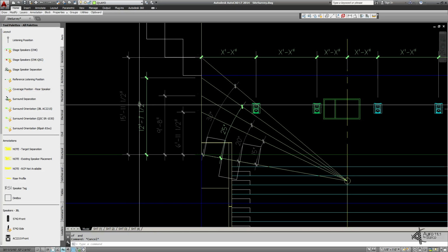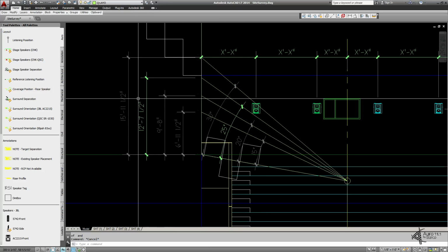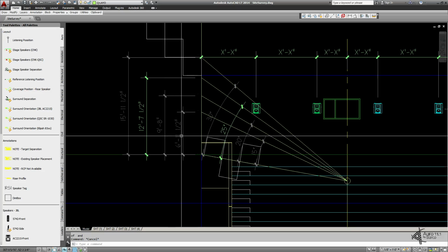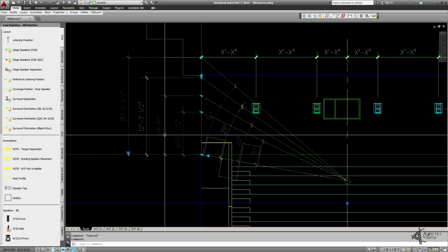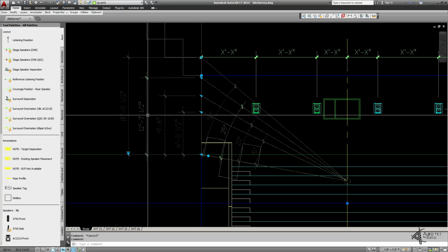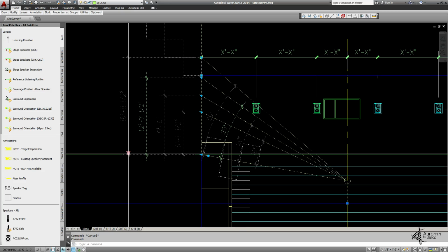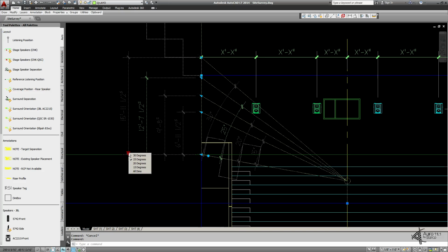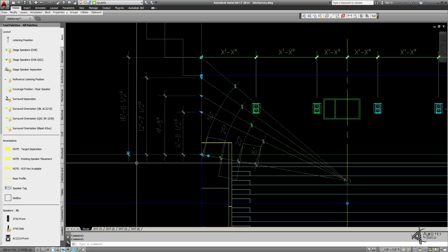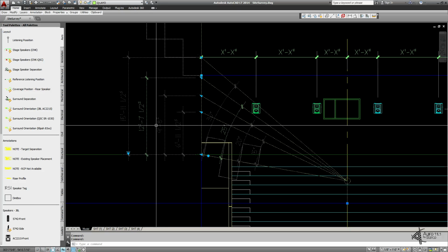And that creates our set of dimensions for the various angles. Then I have it set up so that these print on a layer that's kind of grayed out, so that the angle and set of dimensions of spacing that you're going to use really pop out in your drawing. So then there's finally a little drop down here that you can have it turn them all on, or just highlight a certain degree and its associated spacing.